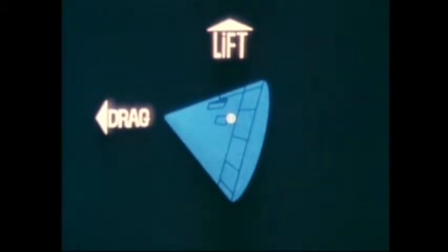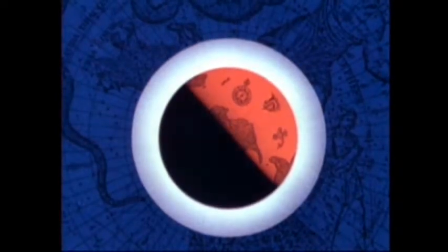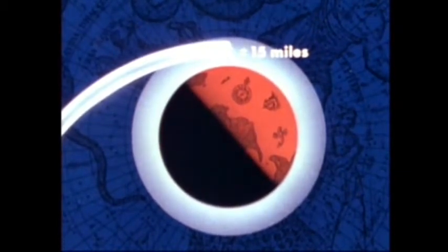The center of gravity is fixed relative to the spacecraft. By rolling the spacecraft about its center of gravity, the direction of lift can be changed and aerodynamic control achieved. We can now see how this affects the limits of the entry corridor. If the entry angle is steep, a lift-up attitude can be held to bring the spacecraft onto a safe entry path. If the angle is shallow, lift-down can achieve a safe entry. Therefore, the entry range or entry corridor is expanded. The spacecraft must be controlled to arrive within slightly less than plus or minus 15 miles of the desired vacuum perigee altitude. This after falling along the return trajectory of over 250,000 miles.